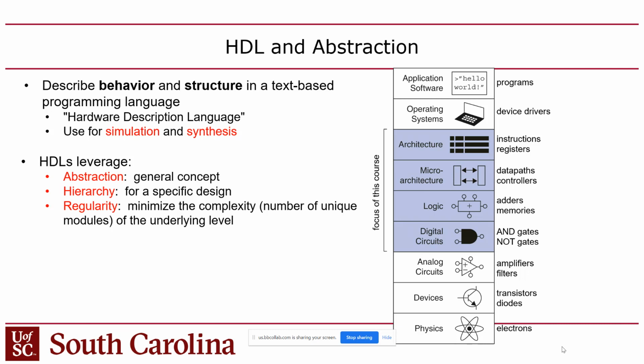And because of the way the hierarchy is arranged, when you go to put it on an FPGA or an ASIC, you flatten the hierarchy. The hierarchy is there just for design purposes. But ultimately, when that hierarchy gets flattened and all the levels come out of it, and it's just squished down to a big pile of gates and wires, then it becomes the enormously complex design you'll have in a modern CPU or GPU. But the designs are meant to be as simple as possible, so you can debug them and you can expand them and you can read them, basically.